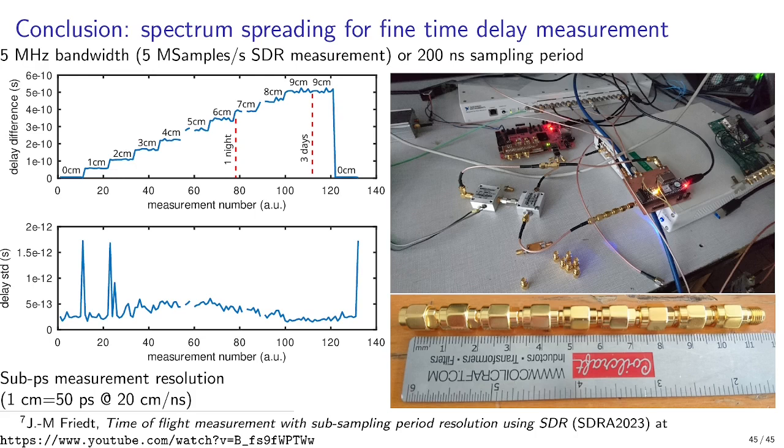to assess the time delay between two channels of an SDR receiver, and indeed we demonstrate how, using only the 5 MHz bandwidth as allocated by the Telstar satellite propagating the two-way satellite time and frequency transfer for intercontinental time and frequency comparison, the 200 nanosecond sampling period is greatly improved on this tabletop experiment with perfect signal-to-noise